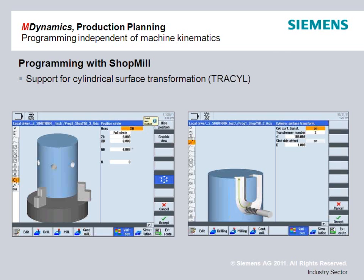The tracefill function is one that we briefly mentioned before. This is not much for the high-end aerospace 5-axis market, but this would be more targeted towards the job shop market. This works on mills that would have a rotary table, or it works on lathes that would have live tooling. The idea is that tracefill stands for transformation cylinder, so that we have a round part, and we want to program something like that U on the side as if the surface of the part was rolled out as a flat sheet.